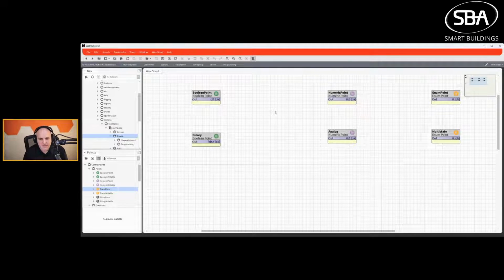Now, I know some of you are like, Phil, I can change them in ABC's software. And you're absolutely right. In some manufacturers' software, you can do out of service, you can do test, and you can override an input to an actual value, but that's just from a test perspective. It's not something I recommend. It makes no sense, because if you need a variable output that you can control, that's where we should move into something else, which I'm going to add as our next point here.